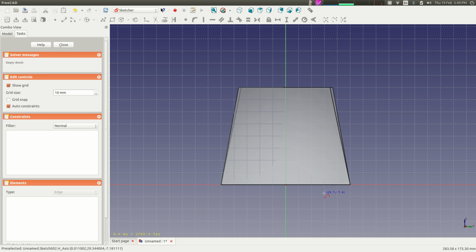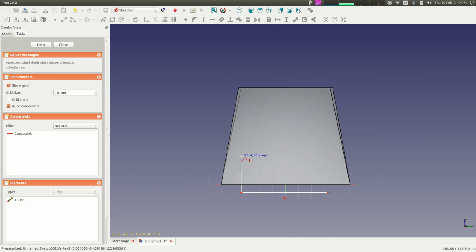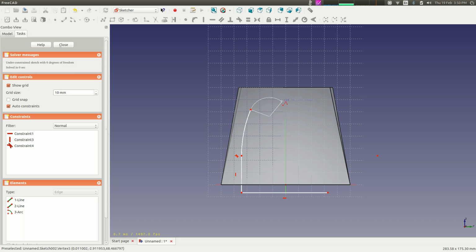I may have mentioned before, but if you hit M while using the polyline, it changes what type of line you're using. So right now it's a straight line. If I cycle M, it'll do a line that's defined by those 2 points, or it can do an arc, or it can do a circle, an inside circle, or a straight line again, back to where we started. I'm going to do the arc, and I'm going to cycle again to do another arc, and cycle it again to do another arc, and then I'm just going to do a straight line if I can find it here.